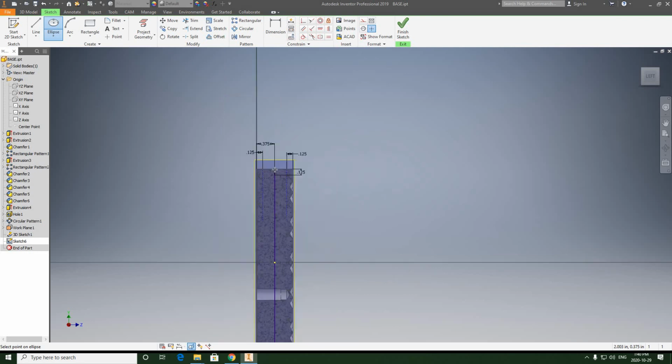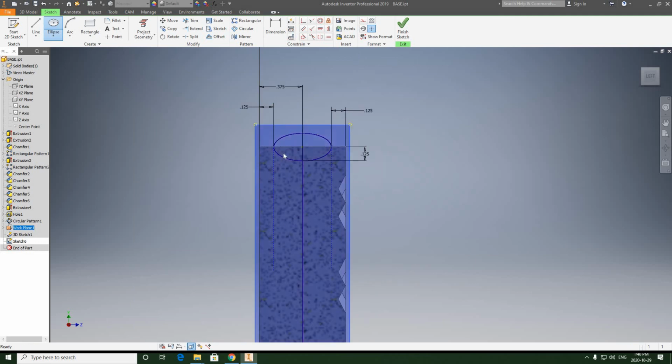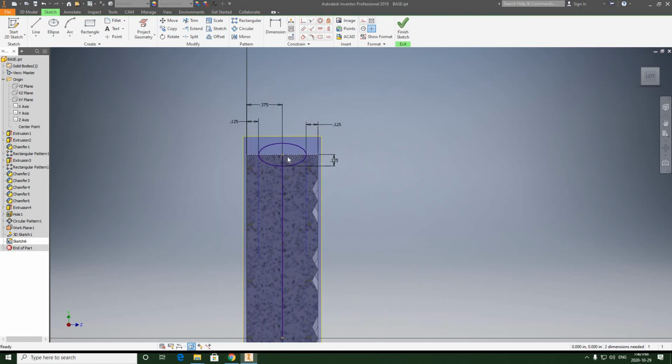Like that. We're going to go from the center and click to the right. This is going to pull the ellipse, and we're going to click the point as the third. So here is first, to the right is second, and then come down, click the point as the third. And that's going to create our elliptical circle, fully constrained right from the get-go.